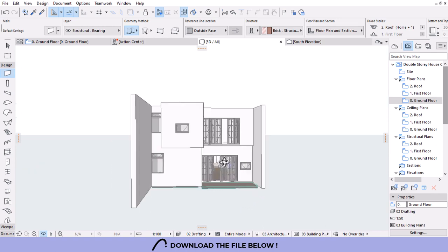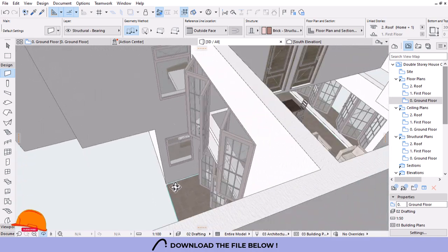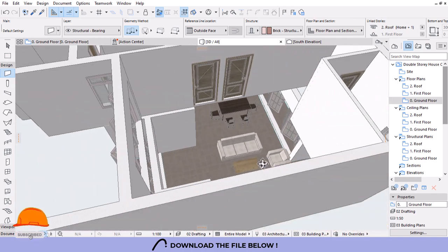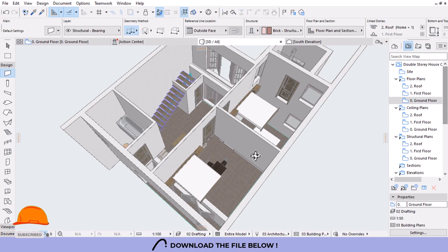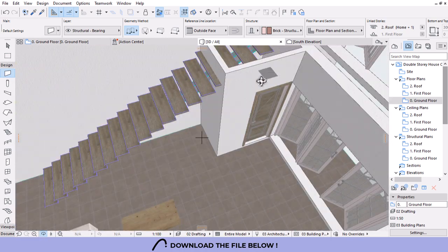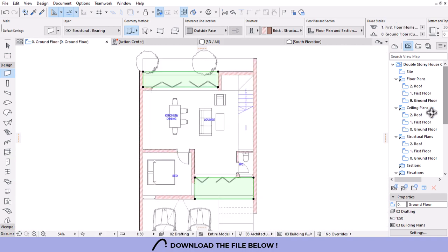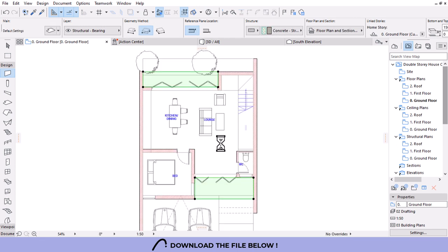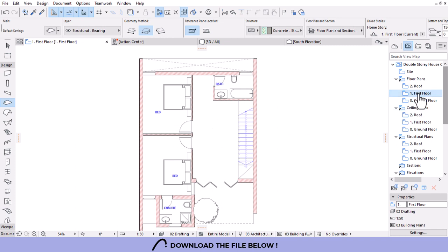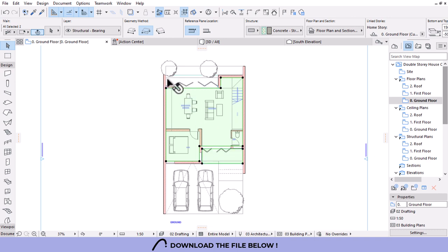This looks better. And then we're going to place a slab for the upper floor, because here we have already placed one, and as you can see, our staircase will go across the height of this toilet to get its support from the slab. Let's do that. I'll pick the parameters of the slab, then go back and copy this, and then that, then Control C to copy.